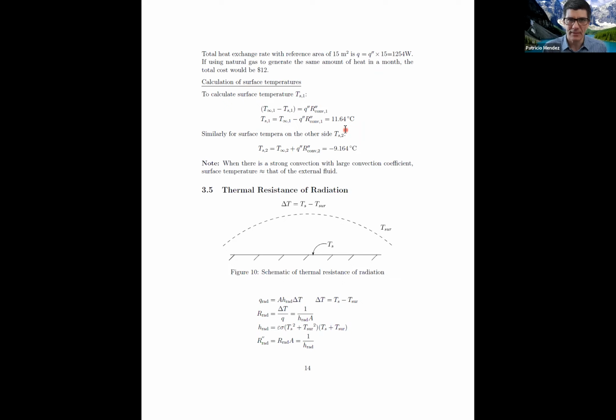So in many cases, we can say radiation can be calculated much like convection, but assigning to it a radiation equivalent convection coefficient that has nothing to do with convection, but looks like convection, including the proportionality between Q and delta T. Of course, the proportionality constant happens to be not so constant, but we call it constant, right? And in many cases, that's okay.